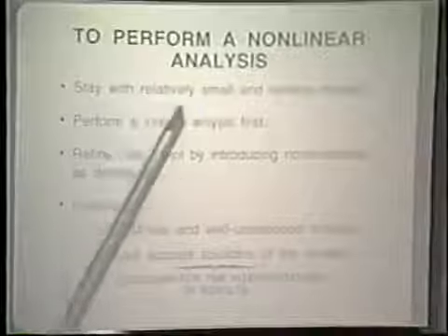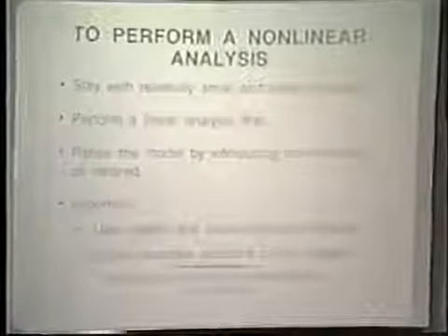If necessary, a first finite element model is set up, and this finite element model is then refined as need arises. To perform a nonlinear analysis, we want to altogether stay with simple, relatively small and reliable models. We always want to perform a linear analysis first.